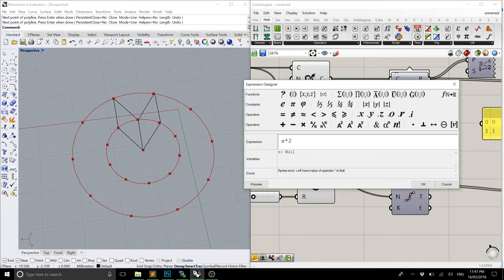For those of you who are familiar with computer-based maths operators, Grasshopper has given you the functions in the top bar. If you hit the times button, that'll give you the asterisk. If you're not familiar with asterisks and times, or for example, / is divide, you can instead use this division operator, and that'll give you a /.